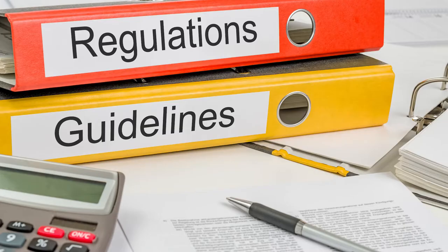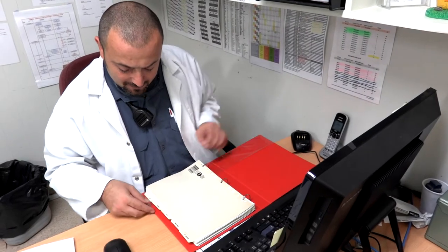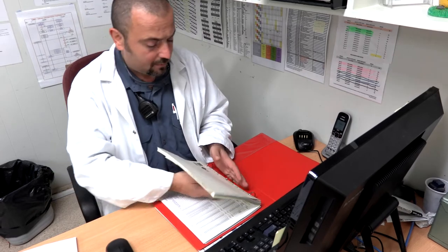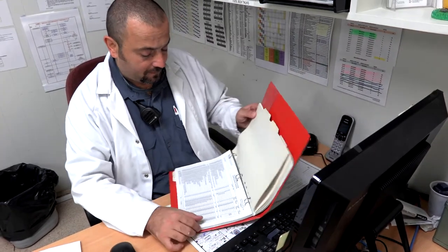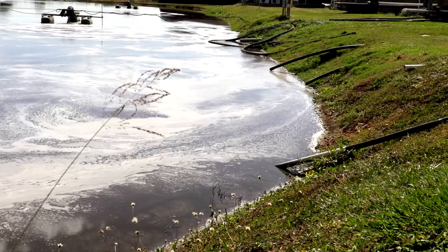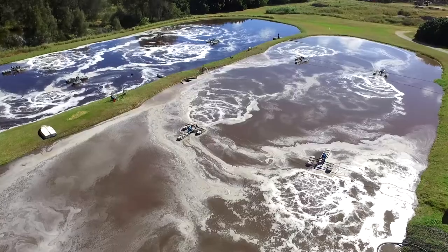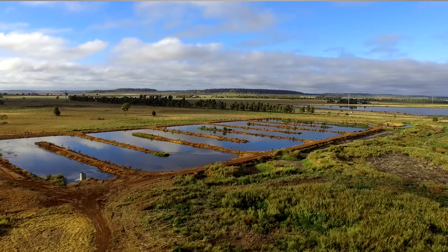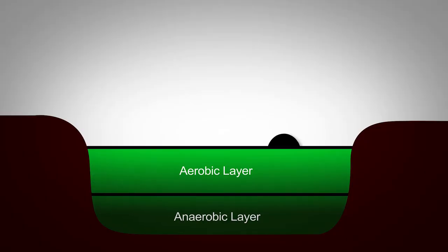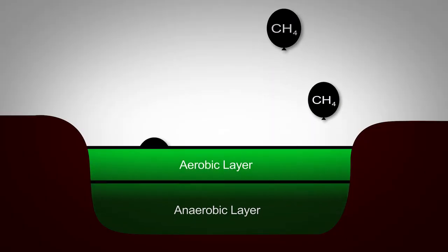Site-specific regulatory requirements concerning aerobic ponds will be stated in the facility's Environmental Protection Licence, Permit or Approval, which is issued by state government. Probably the most common requirement is for the pond to have a certain freeboard to prevent overflows. Well-managed aerated and maturation ponds will have zero emissions. The only uncertainty would lie with facultative ponds.